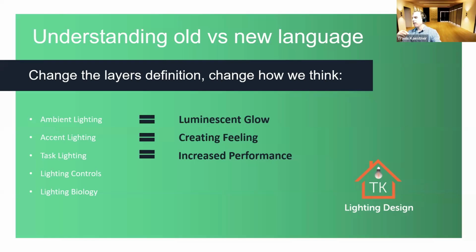I'm straining because of inadequate light levels, and then you come in and just add the task lighting, which is higher amounts of light, usually like 70 foot-candles suggested on a counter space. Excuse me, so you can really see what you're doing. But you don't want that on all the time because that's a lot of light. So that's why it's a task. It's just something that you turn off and on specifically for when you need it.